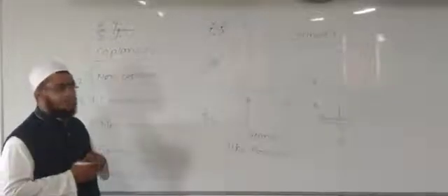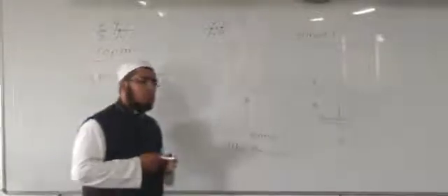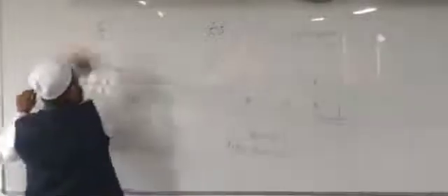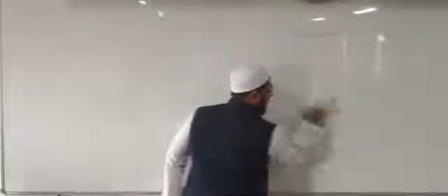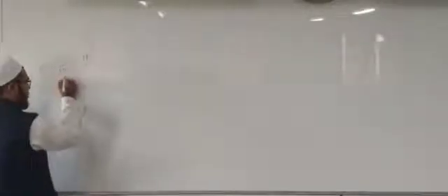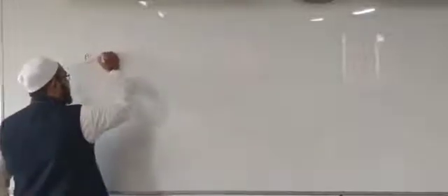Along with these fundamentals of physics, laws of physics and the force systems, there is one law which is called the law of transmissibility of force. The law of transmissibility of force states that a force can be shown anywhere along its line of action. The effect of the force does not change. Means, for example, a force F1 is acting at point A. I will extend the line of action. Line of action is an imaginary line which can be extended infinitely.